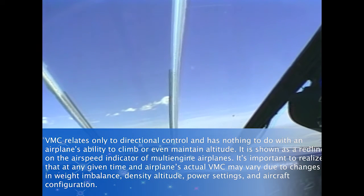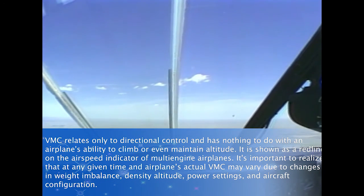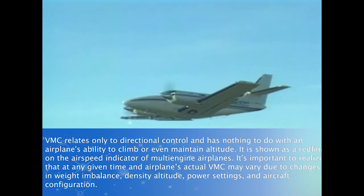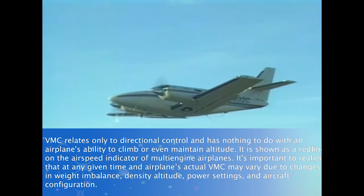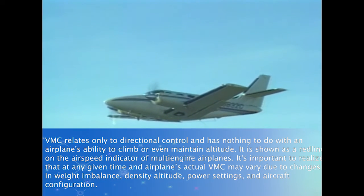VMC relates only to directional control and has nothing to do with an airplane's ability to climb or even maintain altitude. It is shown as a red line on the airspeed indicator of multi-engine airplanes. It's important to realize that at any given time, an airplane's actual VMC may vary due to changes in weight and balance, density altitude, power settings, and aircraft configuration.